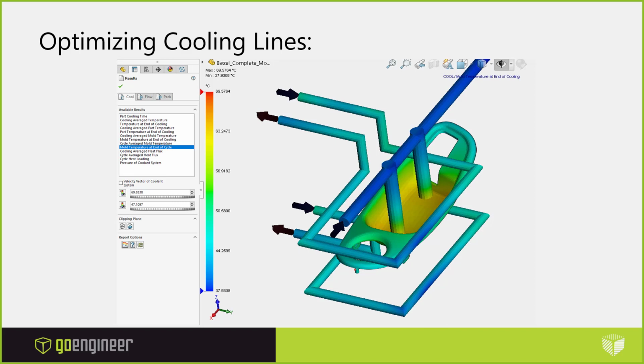So if we're looking at the cost on this project, our cooling analysis is done after the initial mold design, but prior to cutting the steel. So we're validating our mold design. It'd be a really huge cost saving to see that there was this hot spot in the mold around this core that we could possibly improve the cooling there, which would also improve our cooling time on our part model, which is going to reduce our cycle time.